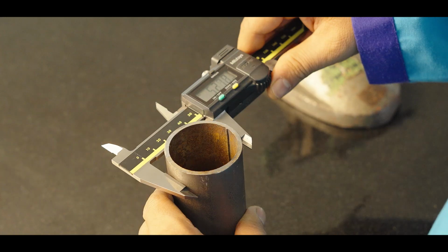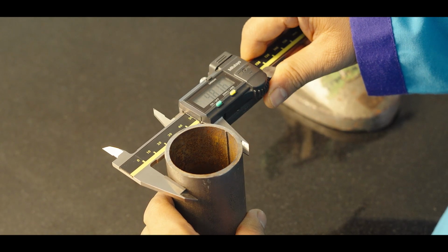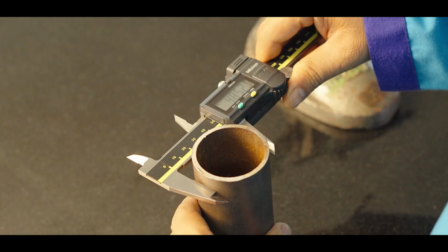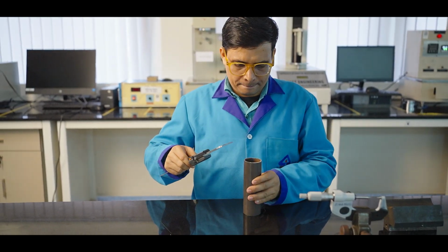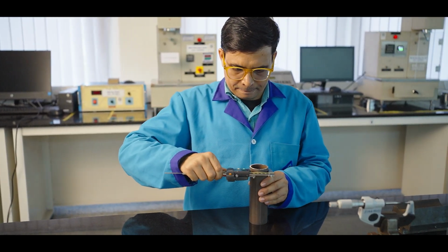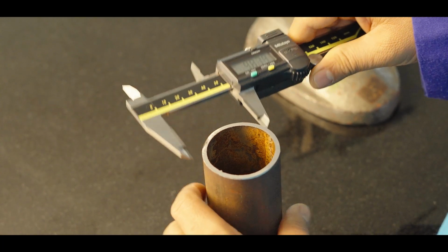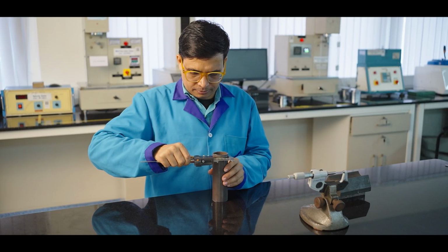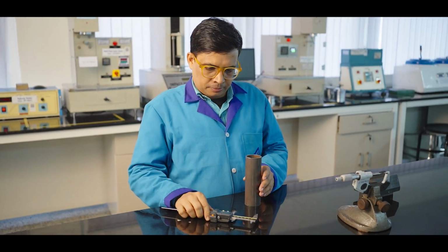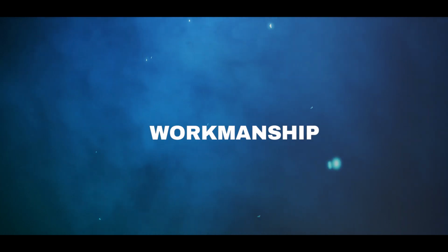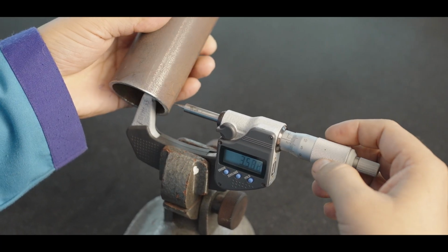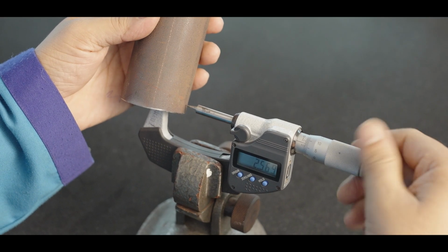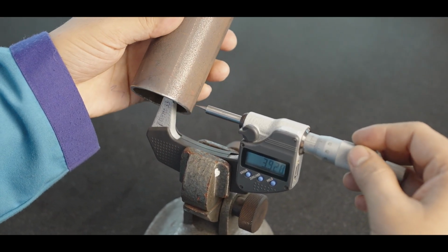Dimensional parameters like thickness, outside diameter are measured using micrometer or vernier calipers. The tolerances on these measurements will be as per clause 6.2 of IS 1161.